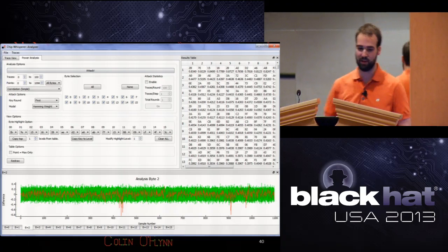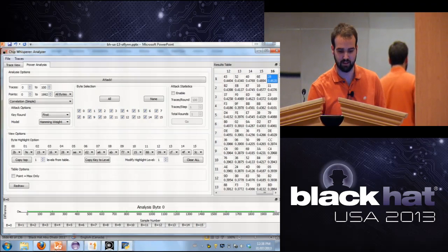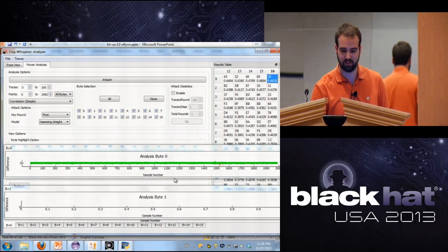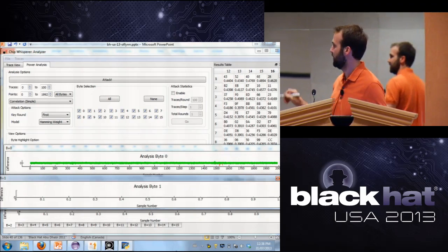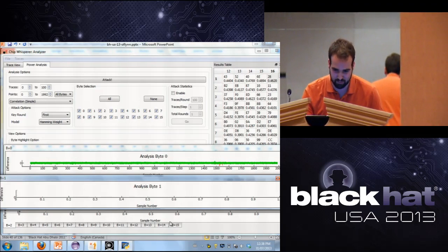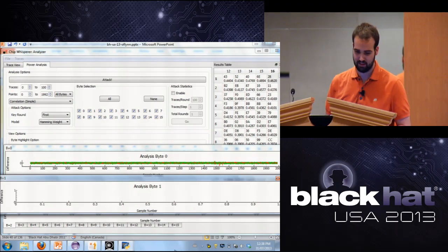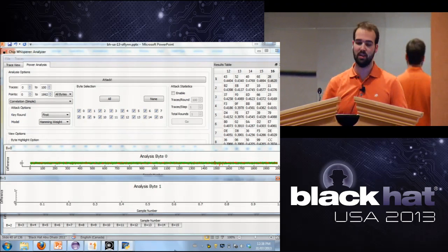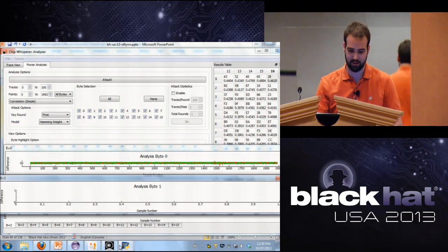And they occur at different times. If I go along to different bytes here, the Python is redrawing, which takes forever. If you go along to different points, you can maybe see at the very bottom here, this byte was occurring around 1500. This other byte, for example, probably occurred earlier on, because maybe it was doing the first byte and then that one. So you end up capturing the window of all bytes, so it may be pretty big.